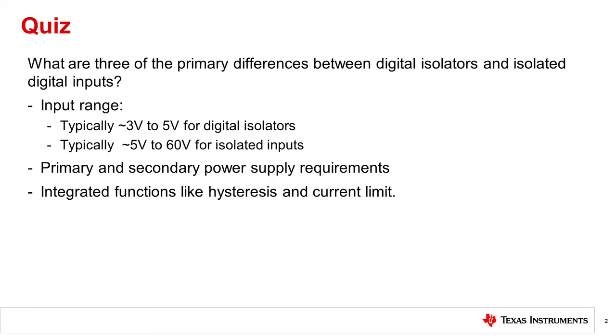Primary and secondary power supply requirements. We talked about how digital isolators require both primary and secondary isolated power supplies, whereas the isolated digital input can use field side input power instead of a primary power supply. Integrated functions. Isolated digital inputs include integrated functions like hysteresis and current limit, and the feature set should be thoroughly investigated before making your isolated digital input selection.